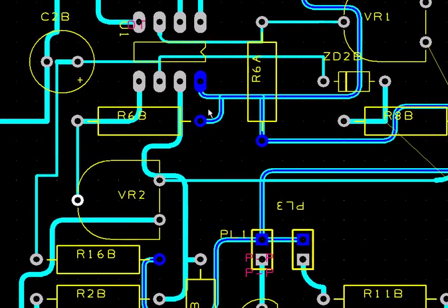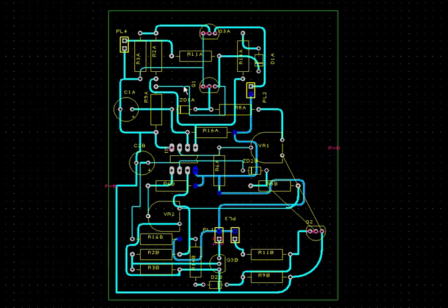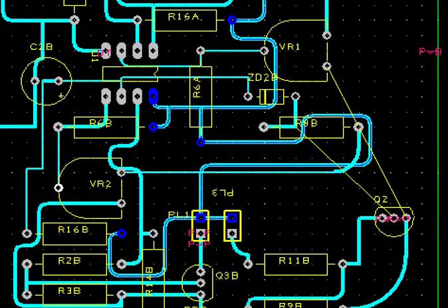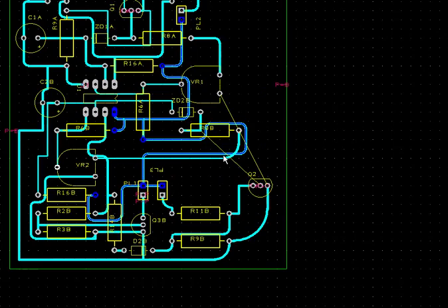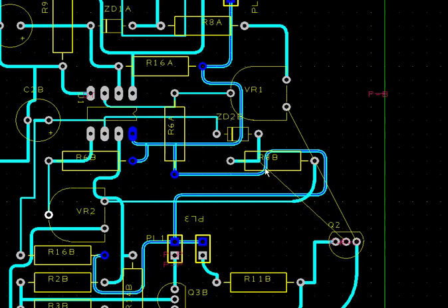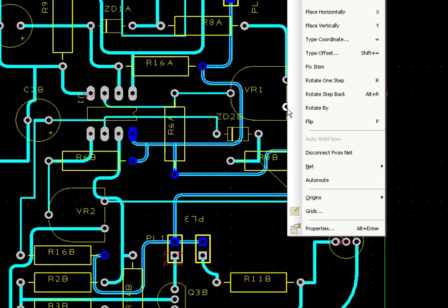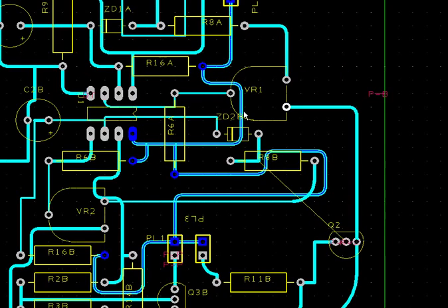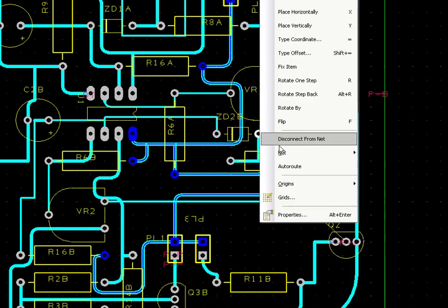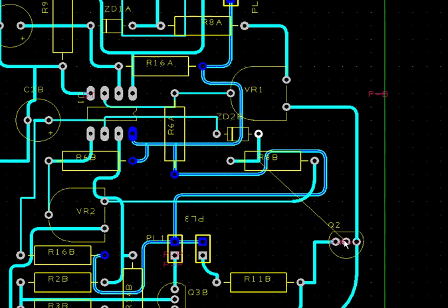Let's just zoom right out a minute, see where we are. Okay, there's a bit more tidying up to do. Yeah, I can move this now. You see, now these need to be routed. Let me just route these. And this one wants to be routed, if it'll go. I can do it manually, or this wants to be removed because it's crossed over. So I'll redo these.